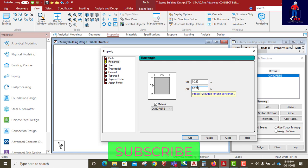They are the ones carrying the building. So the columns at that level can be big. So as you go up, you can begin to reduce. But let us just use the same section, for the sake of this design. So when we now design and some members are failing, we will know how and where and which one to increase, so that we'll be able to optimize in this design.